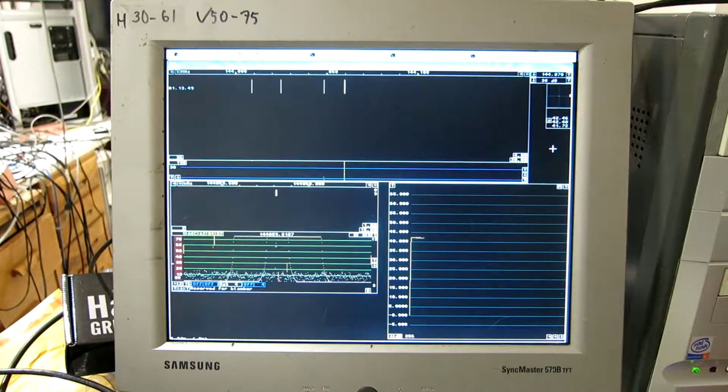So I cannot go down to a lower gain because the signal to noise ratio will lose more than 1 dB. So I have to stay here, and this means that the dynamic range is going to be not quite as good as it was with the higher sampling rate, and I will verify that.